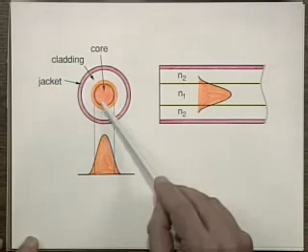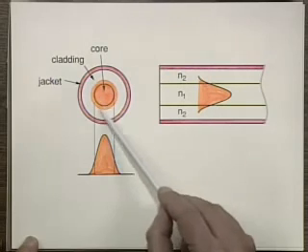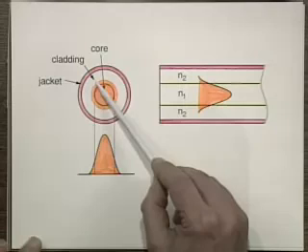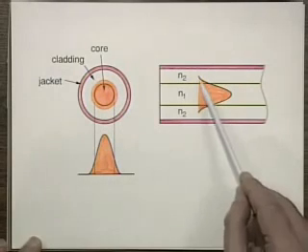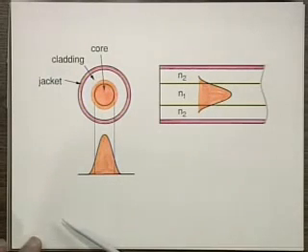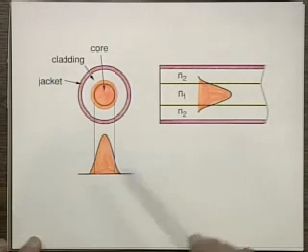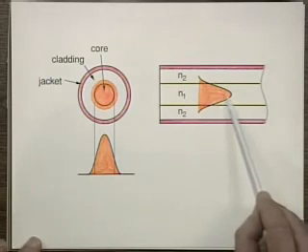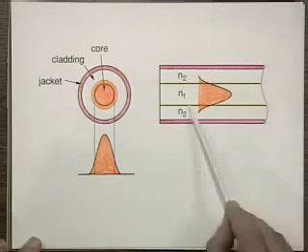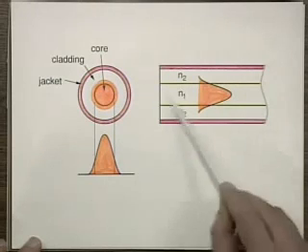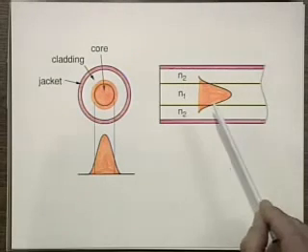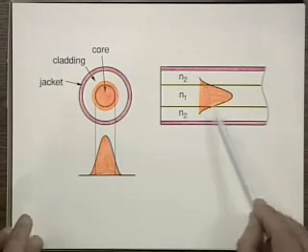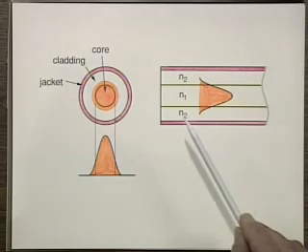So you can see this is the size of the core, but this orange, if you can see it as orange, basically extends beyond the size of the core, and that's what we call single mode propagation. Here's the field distribution, here's the size of the mode. It extends a little bit into the cladding. Most of it goes into the core, part of it goes into the cladding, and propagates right down the fiber. The ray idea is fine for explanation, but when you do the proper calculation, that's what you get for the lowest order mode.